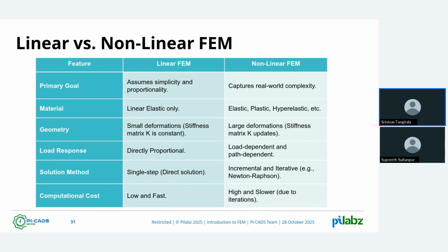What we mean by non-linear is that it takes the dynamic material properties, or the dynamic state of each of the deformations, into account to calculate the next element's solution. So it takes a lot of time, and more complex equations are involved as opposed to a linear equation. The solution method for linear FEM is a single-step direct solution, but for non-linear FEM, it is incremental and iterative, for example the Newton-Raphson method.